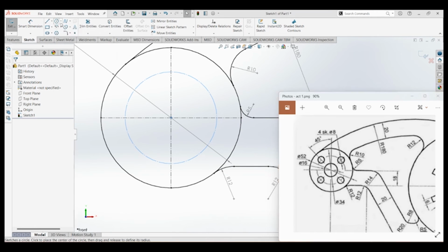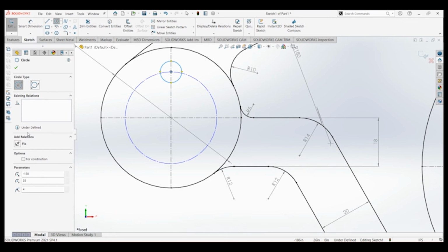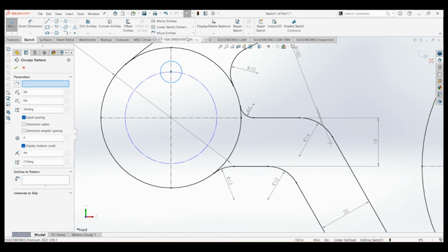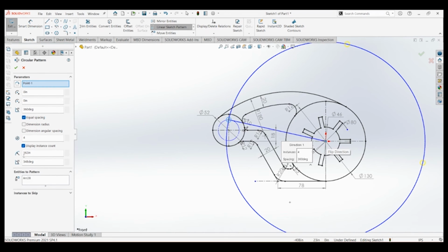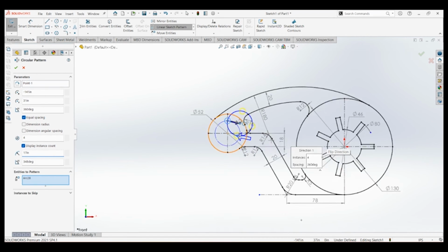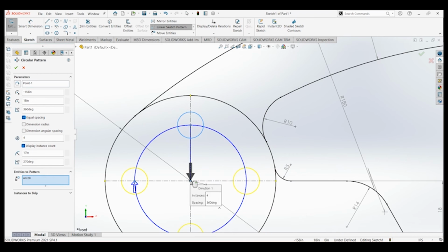Select the circle with 4 as its radius starting at this point. Then use the circular pattern option again to make it look like the figure. I'll just edit this one and input 17 since that's the radius of the construction circle. And I'll also adjust this point up to here since this is the needed origin for this circular pattern.